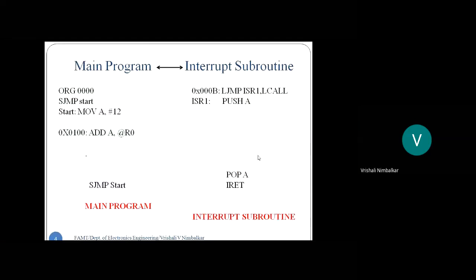So usually what is done? No doubt, when an interrupt arrives, the microcontroller finds the return address, saves it on the stack, and jumps to the mentioned vector address. Whenever it jumps to the vector address, it disables all the interrupts, and at that vector address we write a jump again to somewhere else. Either write a long jump instruction or a long call instruction.